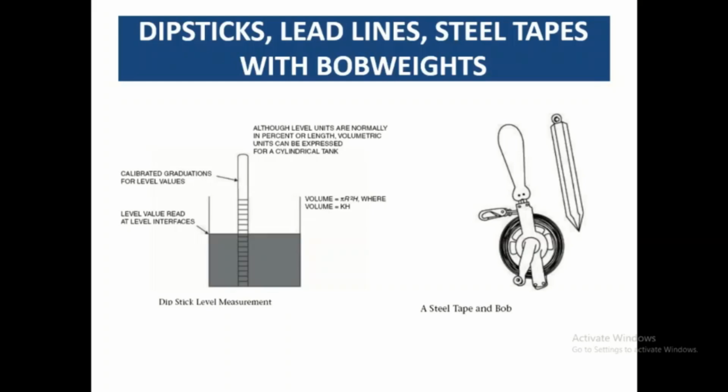But that steel rod is much larger, and it has limitations, because you need to put it into the liquid and then remove it to use in another part. So it is an old, traditional method of level measurement, and most of the time it is used for open tanks present in the storage area, not in your process area.